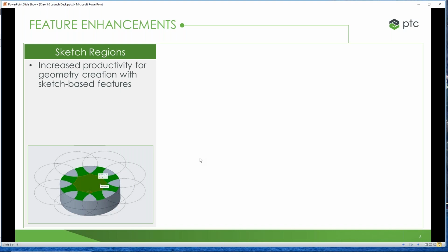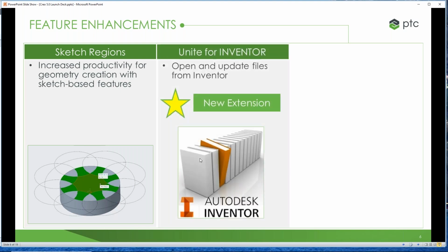One of the things, in a non-disclosure type of thing, to make sure that we're on the level, is that you cannot write out an Inventor file. You can write out, there's a collaboration extension, right, that allows us to write out a CATIA file or an NX file or a SolidWorks file. This capability for Inventor has not been added to that yet. So we can only bring in Inventor files natively. We cannot write out a native Inventor file from Creo or something like that.